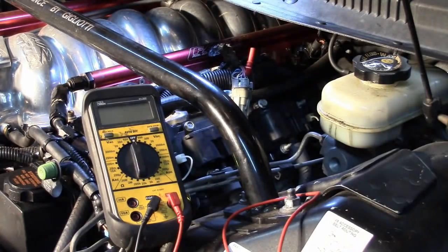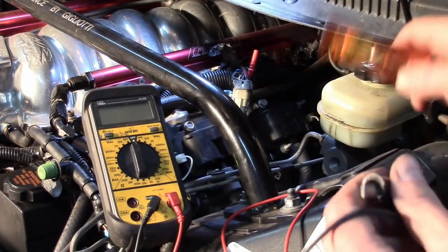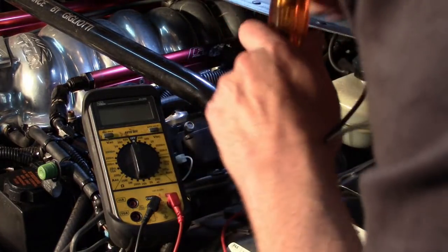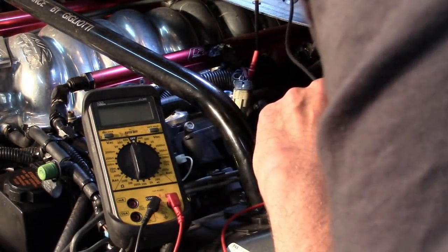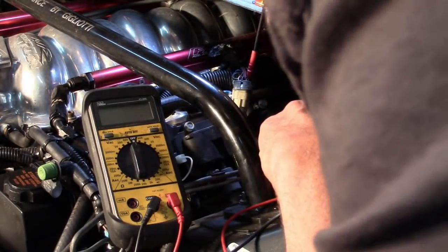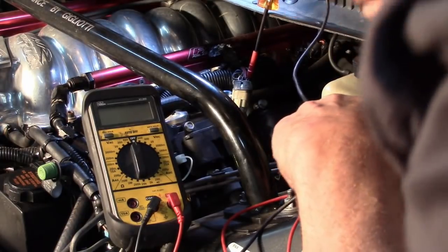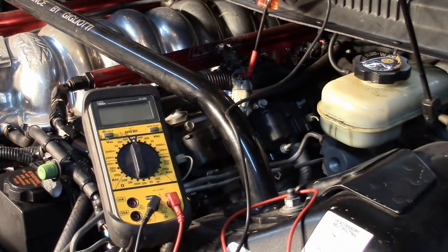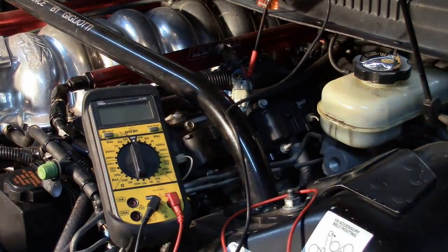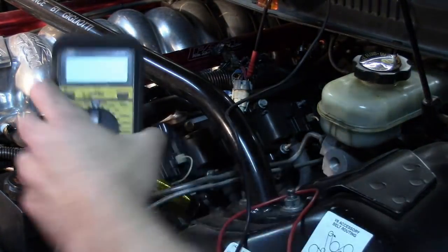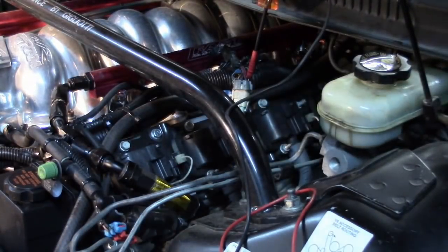So what I'm going to do is get a test light. All right, we know how these work. These are positive feed, so we'll set up accordingly. I'm going to put that test light in there. We're going to see that test light flash. Let's see, that's plastic, so I'm safe there. We're going to see that test light flash, indicating the control from the PCM. And that was not the constant power feed. So we don't need this anymore. Let's go ahead and do that. And of course, you guys know exactly how to set this up.